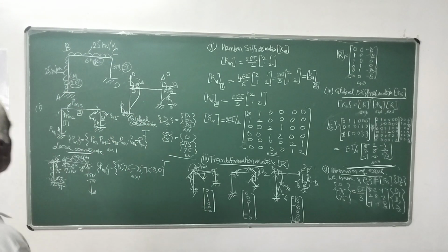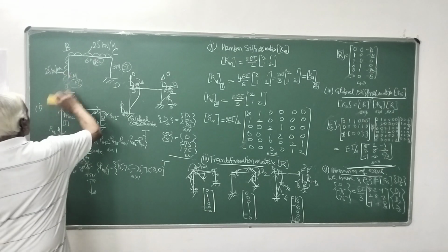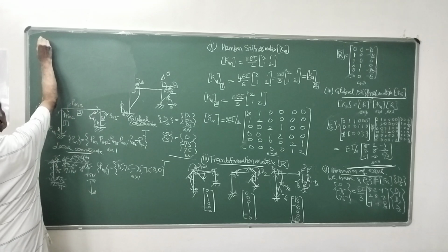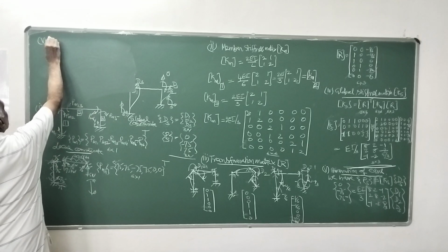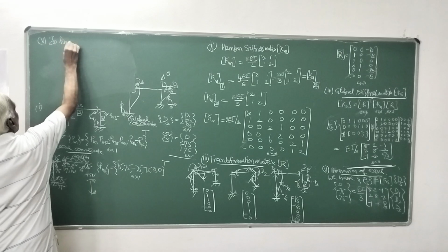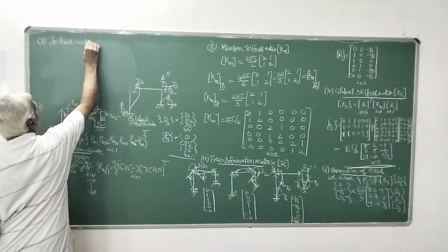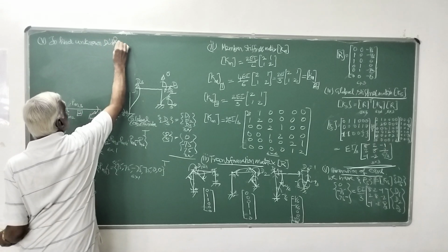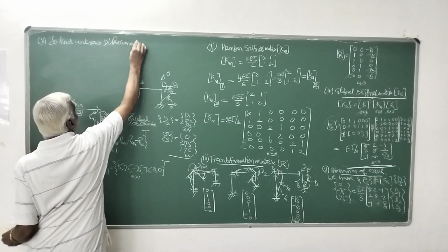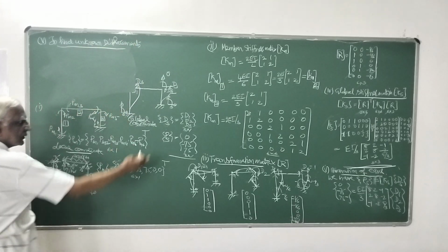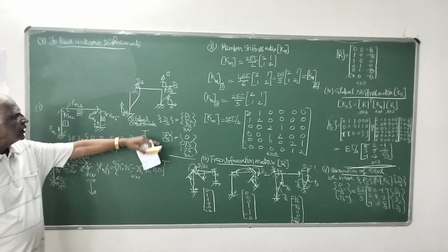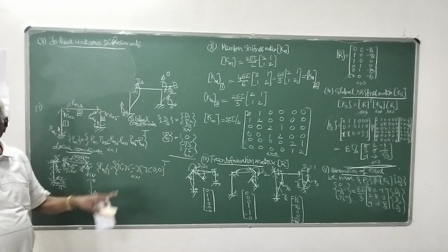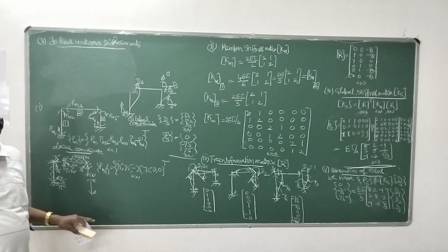The sixth step is to find the unknown displacements. I told you in the first step itself, you have to determine the unknown displacements corresponding to global coordinates, because the loads will be in the global coordinate system.